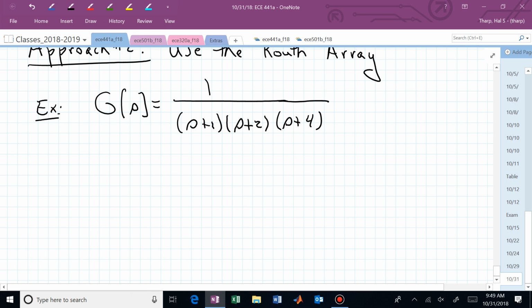Right? So now how do we find the Routh array expression, or we're looking for some polynomial that we can use in the Routh array. How do we do that? What's the closed loop transfer function? Cheer! KG over 1 plus KG. What's the denominator? That's what we're after, isn't it?